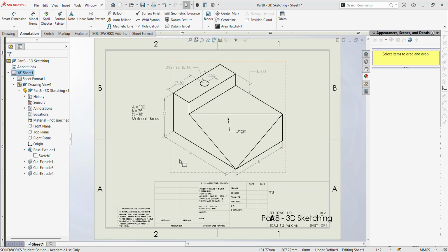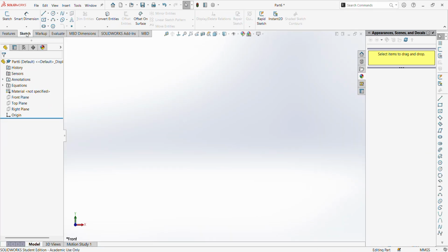Okay, since we're sketching on our front plane, we have A and C as our height and length, and then B will be our extrude distance. So let's make sure to remember that. In other cases, we might have drawn out this side profile, ignoring this triangle cut, and done a weirdly long-bottomed L. But you'll see that would not allow us to use our C very easily. We'd have to use C one time and then cut down the next, and it's a little less worth it when you are skilled at extrude cutting like we are now, right?